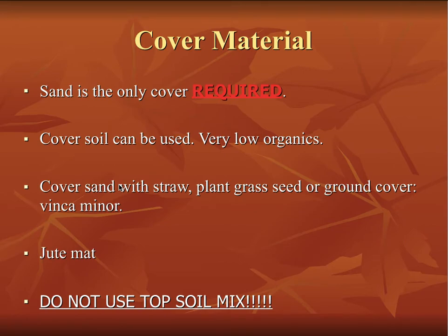So cover material. The only thing that's required is an additional 6 inches of sand on top of where the coils lay. Cover soil can be used, but it's imperative that the soil that's used is very low in organics. I'm going to jump a couple of bullet points, and you'll see down here, do not use topsoil mix. So if a homeowner wants to plant things on top of the drain field, more power to them, but if they go down to Home Depot and just get the best gardening topsoil mix, that's very high in organics, and that capillary rise of the water will stay there, it'll get stuck there, and you'll have a perpetually mushy drain field. So not topsoil mix.